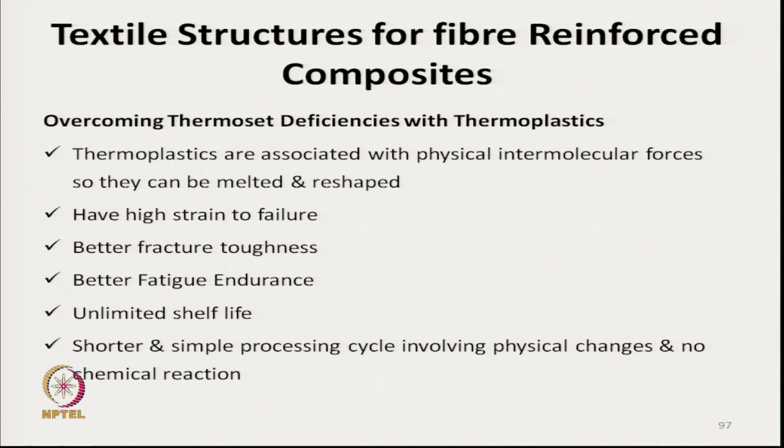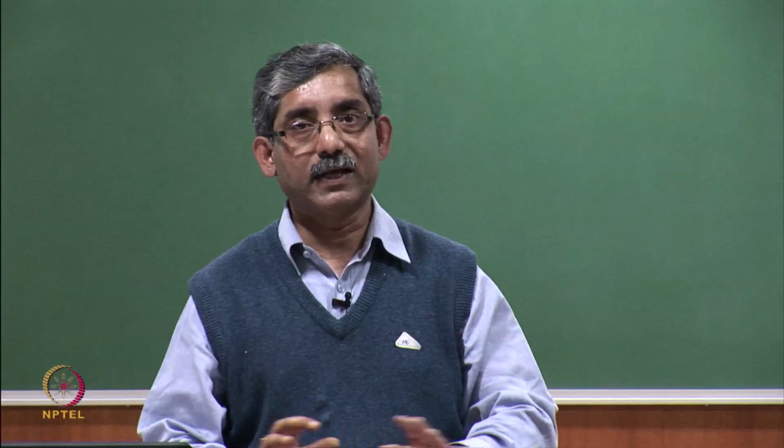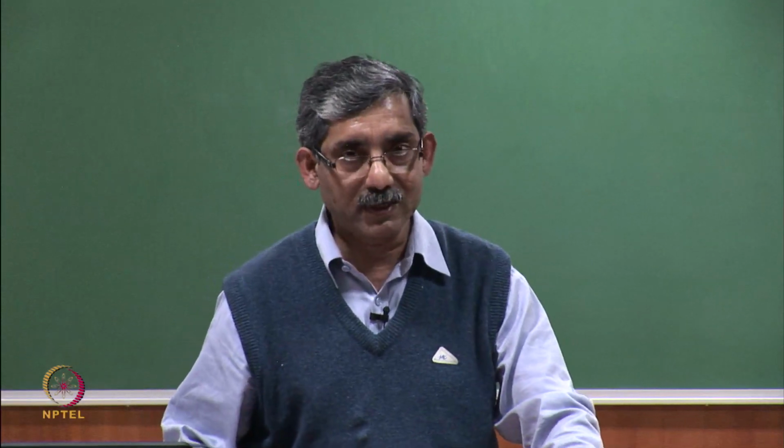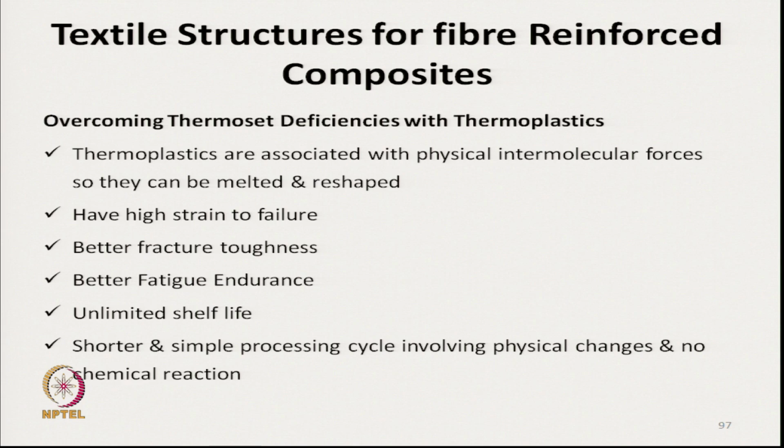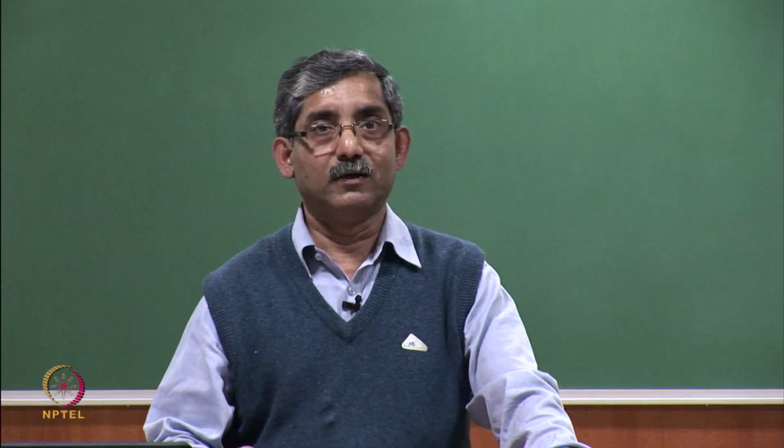See, in thermoset matrix we have discussed the limited shelf life. If we preserve the thermoplastic matrix properly, the shelf life is very high, and another important characteristic is a shorter and simple processing cycle involving only physical changes, no chemical. By heating it gets melted, and on cooling it solidifies again, no chemical reactions are there. So, that makes the thermoplastic matrix so popular.